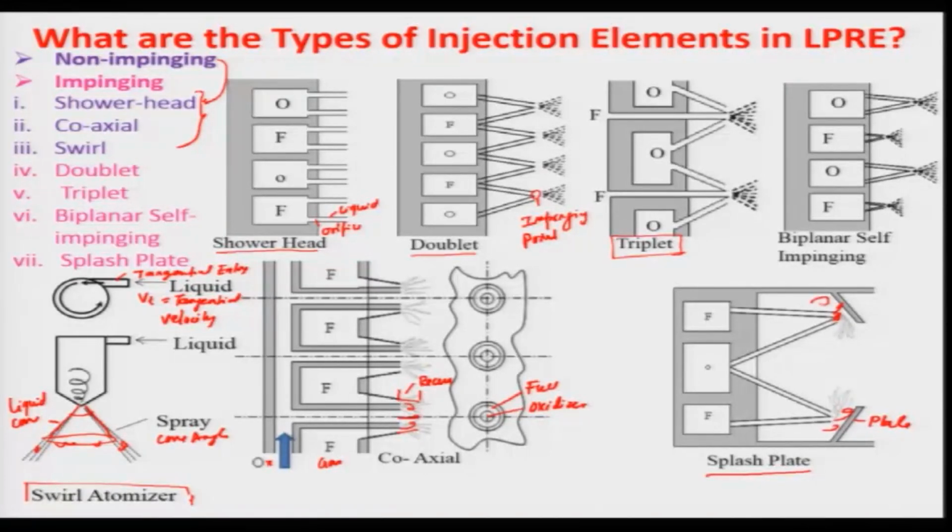recirculation zones which may affect that, and as we know, the fuel should be near the wall region so that it acts as an insulating layer, and besides this, the oxidizer should not come in contact with the high temperature wall, so that it does not get eroded. And besides this, if some of these fuel oxidizer mixtures get ignited, it may lead to a little high pressure in this zone and lead to an explosion, provided it is not properly managed.